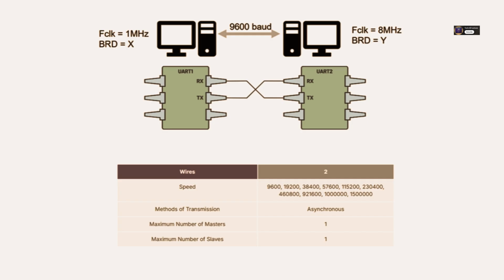The generated rate usually needs to be within about 2% of the target rate for reliable communication. Any more deviation, and you risk those sampling errors creeping in. That's why stable clock sources, like crystal oscillators, are often important. Okay, so accuracy matters a lot.